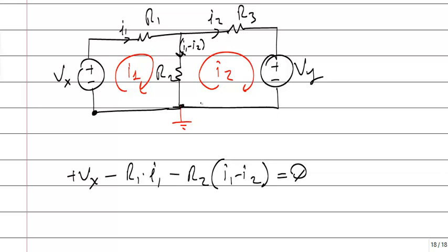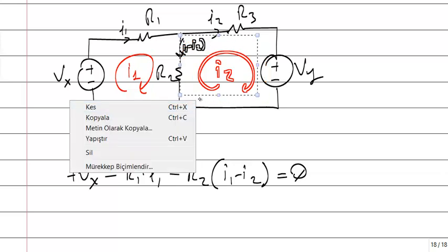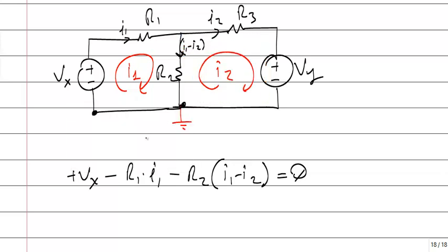Okay. The loop equation or KVL equation for the second loop. Start from the left bottom here. This current causes a voltage drop if you come from the upper side. But if you go from down to up, there will be a voltage increase, because I have defined this as the positive side and this as the negative side of that resistance.